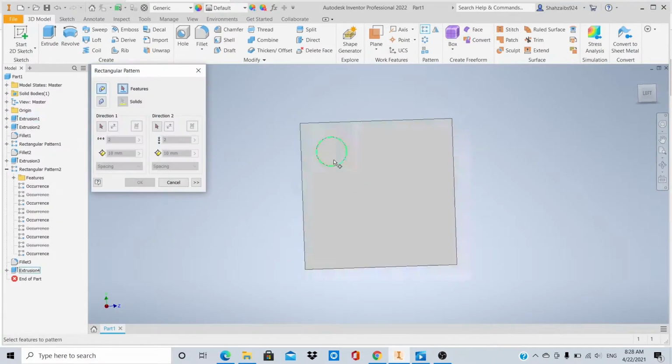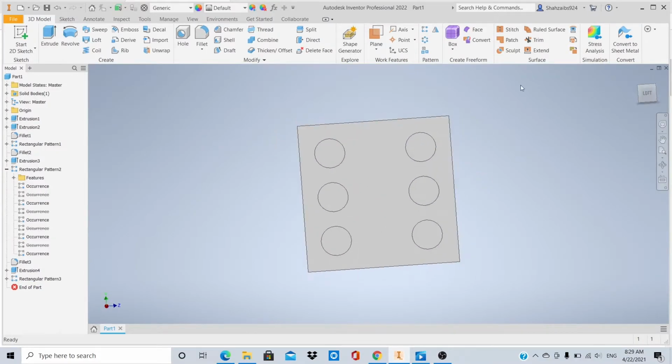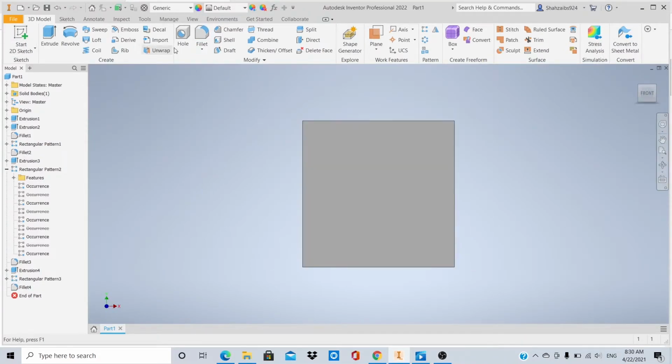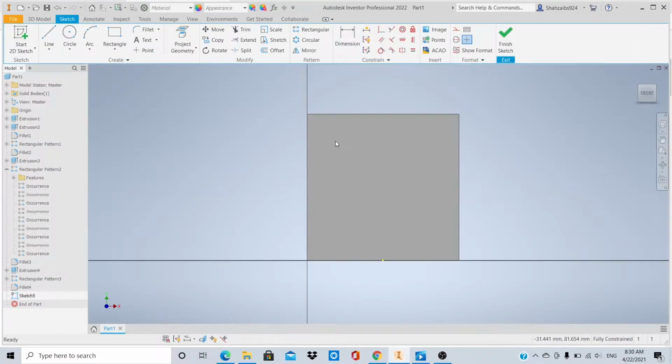Another useful tool that I learned was the workplane tool. Usually one would have to sketch on the surface of an object to create changes or edits or anything like that. A workplane allows one to add a sheet to sketch anywhere he wants and add objects wherever he wants. The workplane feature also allows one to create an extrusion parallel to any object, and you can also adjust a workplane angle wherever one would like to do so. I used the workplane tool to create a number of objects.